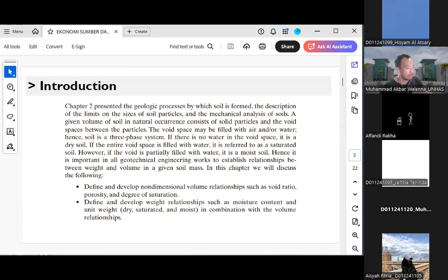But water, which is liquid, is completely different from the solid grains in terms of stiffness. It means that the amount of friction generated is comparatively much weaker in comparison to the solid-solid contact. So when it comes to soil behavior and its strength, it's going to be comparatively weaker when you have more water and air in comparison to when you have less of them. That's how I can explain the strength.